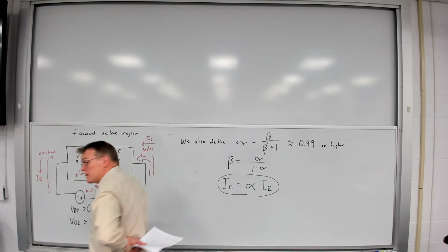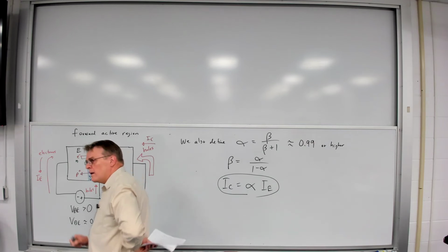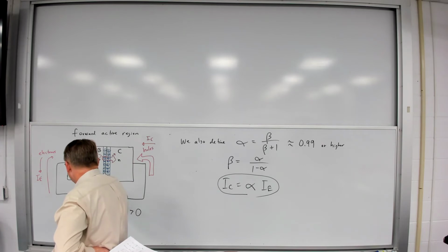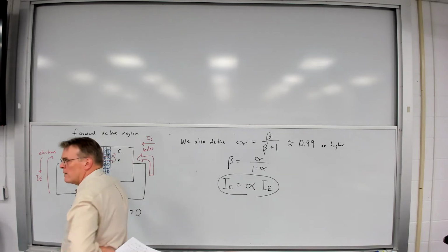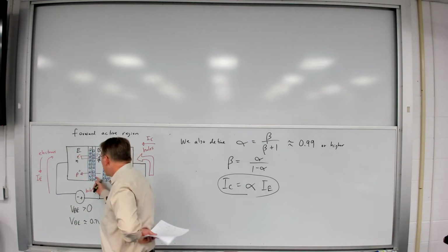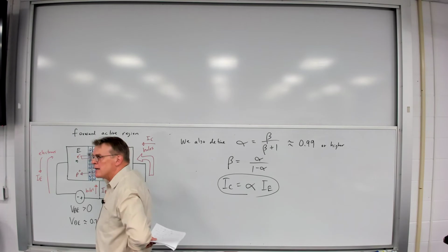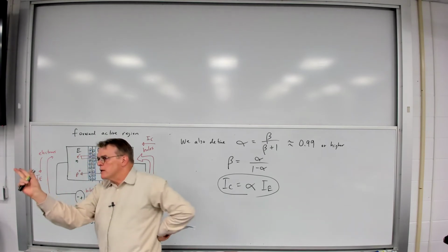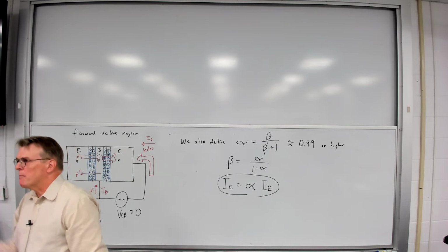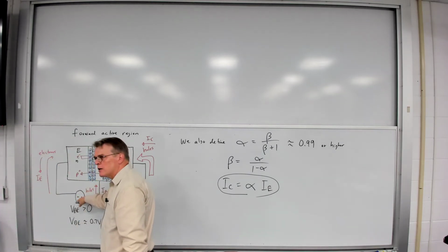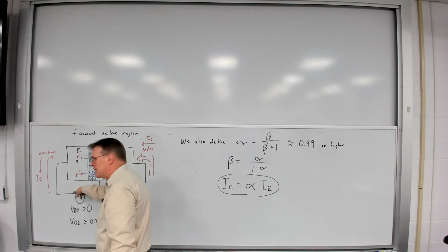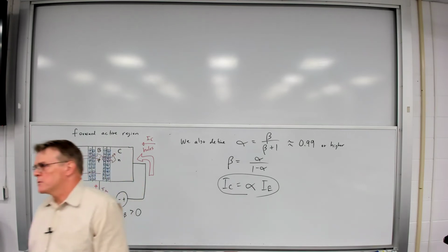Without the current that's going through the base, without IB, you can't have IC, right? Yes. We've got to have base current. And the reason is the base current flowing is what forward biases this junction and causes the depletion region to narrow so that carriers can diffuse across it. So that's what forward bias does. You've got to forward bias the junction. And then you're going to have holes flowing into the P region because you're connecting that source to forward bias it.